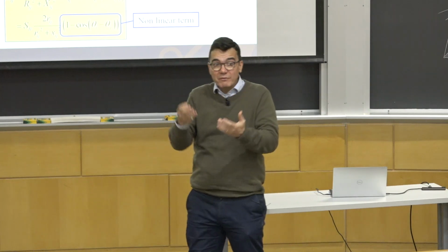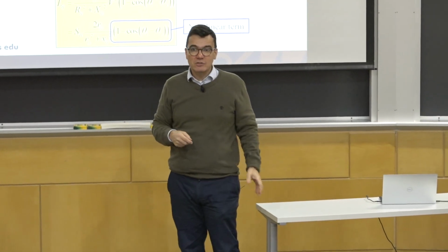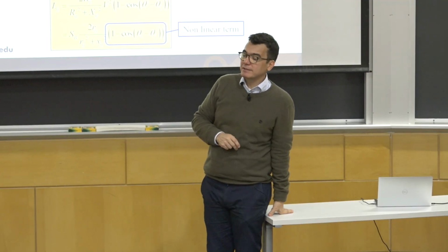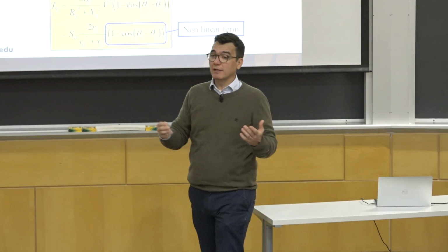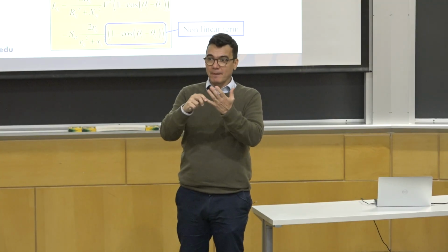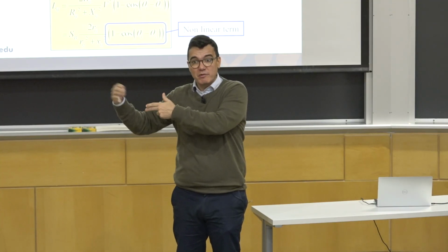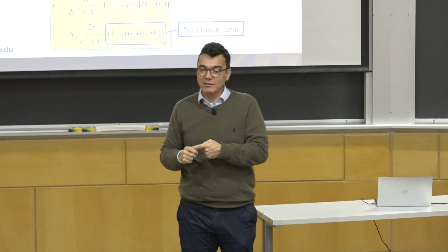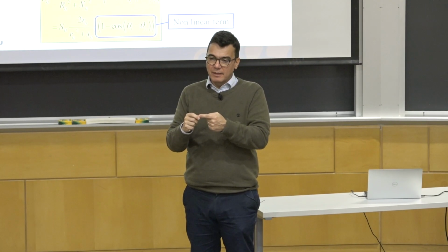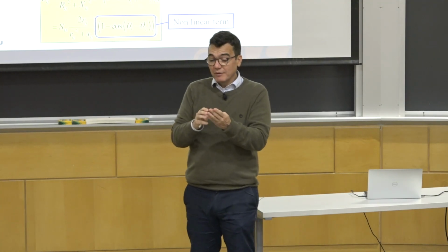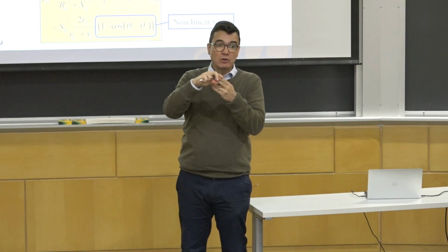So we can work everything in per unit. And this simplifies a lot the manipulation and the calculations of these electrical systems. This means, how many degrees of freedom do we have? Well, basically in a power system we have voltages, currents, impedances, which is the equivalent to the resistance in direct current circuits, and power, okay?